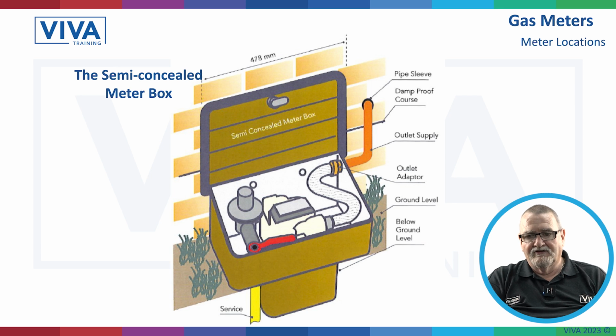The bottom part is going to be below ground. You've got the ground level which comes across, then the outlet pipe is coming through. The pipe should always go through into the property above the damp proof course, not below, because if it goes below the damp proof course, we're going to get damp going into the property and then the customer's going to be causing problems. So again, if you're doing a first fix and there's a subterranean gas meter there, first fix is you're the first person putting pipework in, you'd always go above the damp proof course.